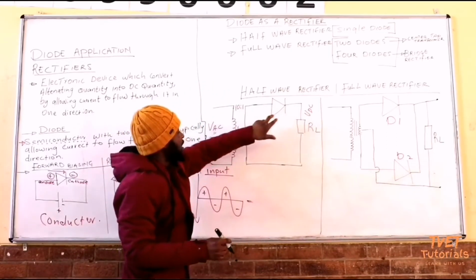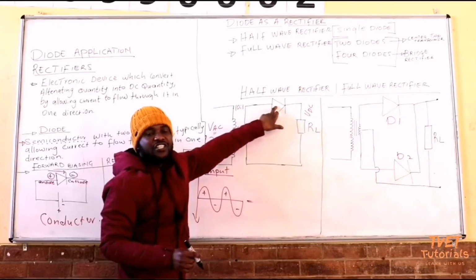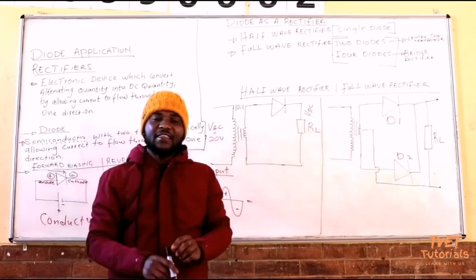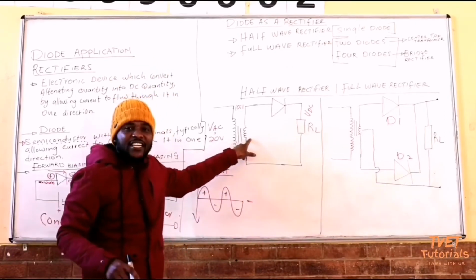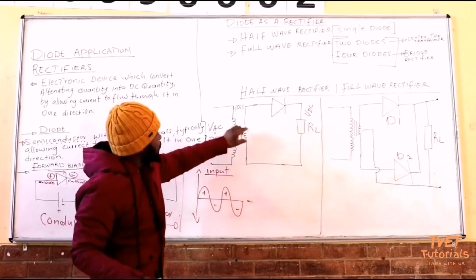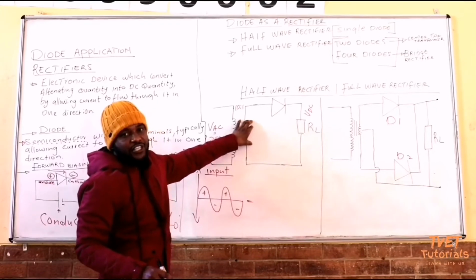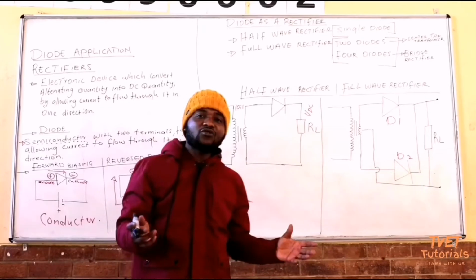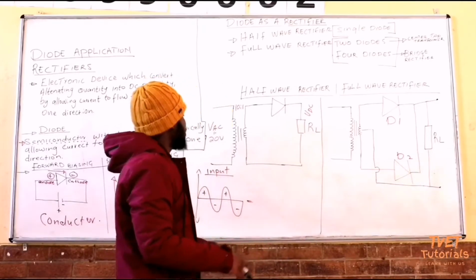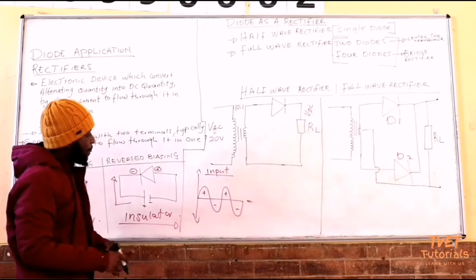But what you are going to supply to your rectifier, which is the diode, it has to be the maximum value of the secondary voltage. That's what you are going to apply to the diode, right?